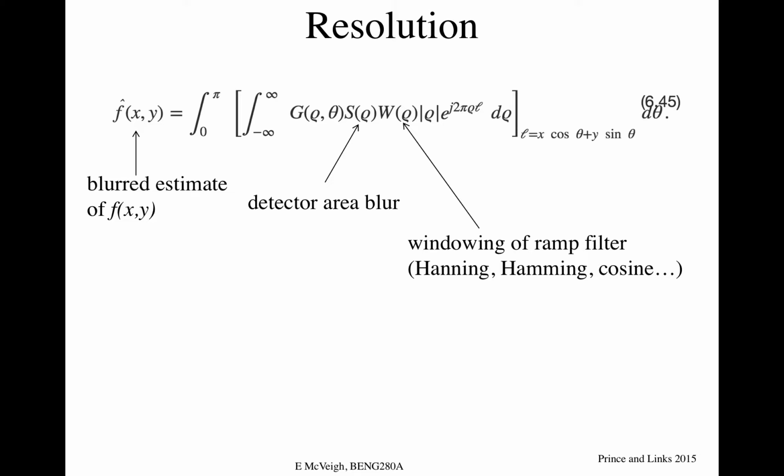So if I have a 1 millimeter detector, all of the signal coming inside that 1 millimeter spatial separation will be integrated up as signal at that location. That's going to cause smoothing, because it's integrating those different lines across that 1 millimeter detector. We can model that as: what are the spatial frequencies of a tiny rect in the Fourier domain? That's a multiplication from detector blur, and so that acts like a filter.